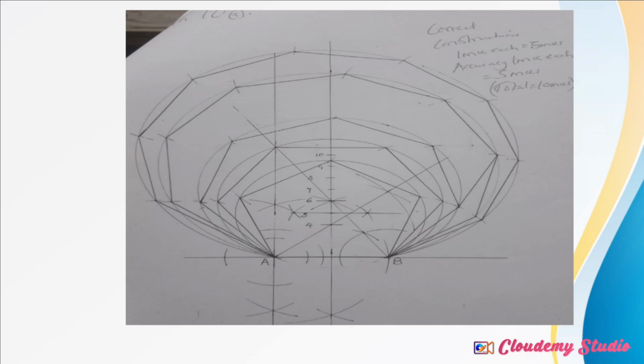So I started by constructing an angle of 90 at point A, which can be done by standing at point A. You stretch your compass to a reasonable radius and make an arc on both sides of the line, that is the left side and the right side of point A, to get two arcs. Standing in both arcs, you can make two arcs above and below. Then you join the two arcs to get the 90 degree angle.